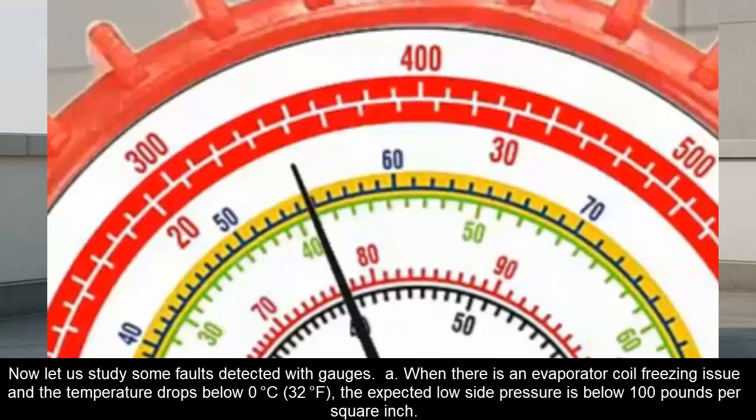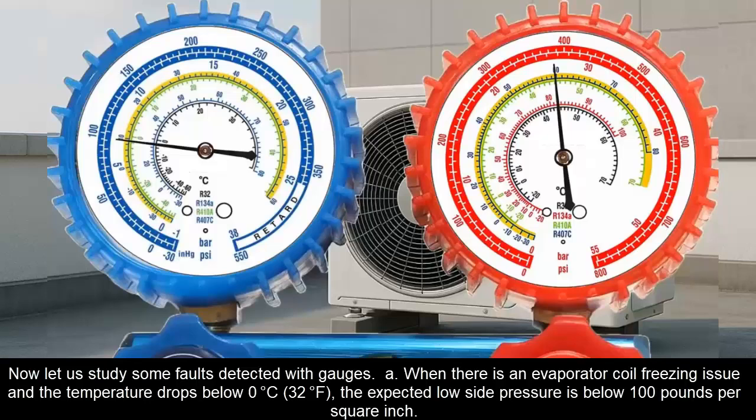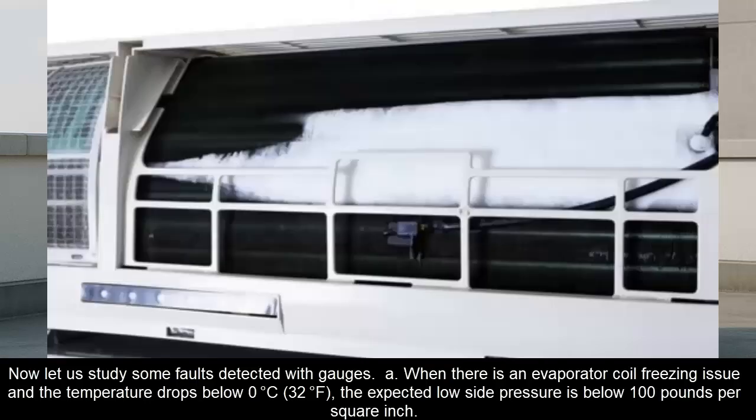Now let us study some faults detected with gauges. A. When there is an evaporator coil freezing issue and the temperature drops below 0 degrees Celsius, 32 degrees Fahrenheit, the expected low side pressure is below 100 pounds per square inch.